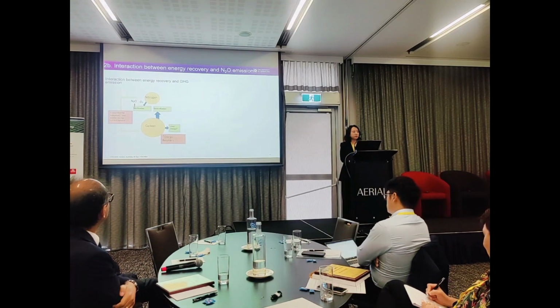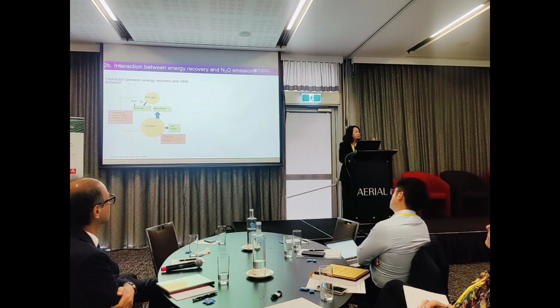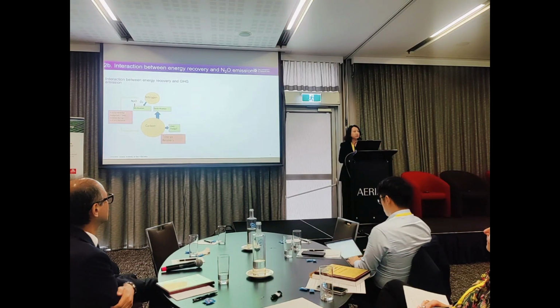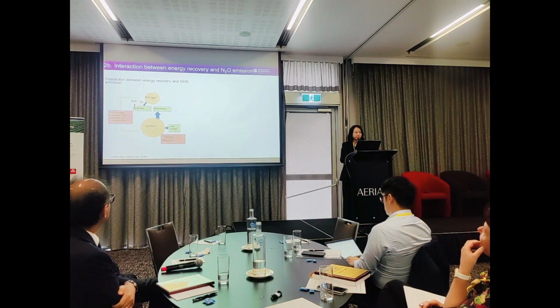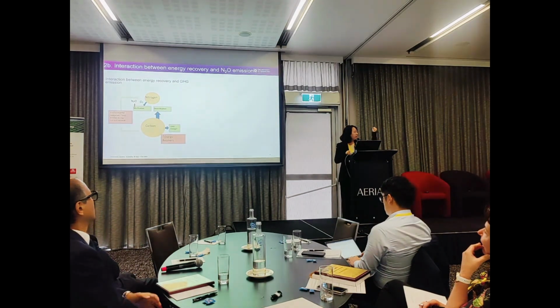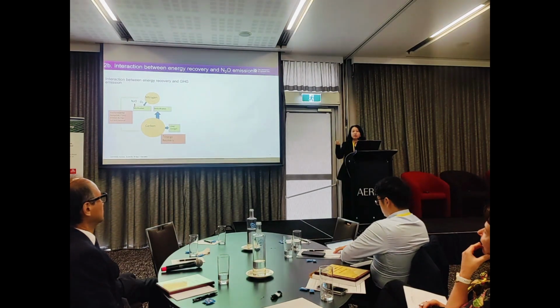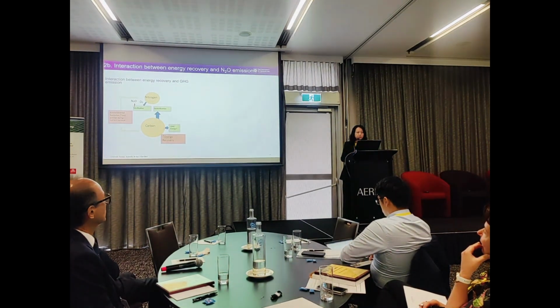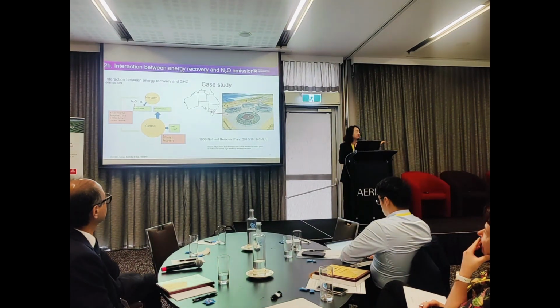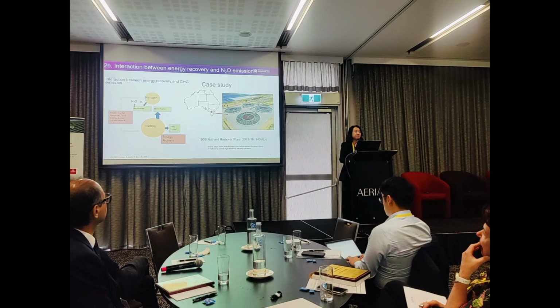Okay, the next thing I want to talk about is the interaction between energy recovery and nitrogen removal. When we try to promote more energy recovery, however, in our existing plants this carbon is also very valuable for nitrogen removal. That's what we need for the denitrification process. So there is competition over how we use the carbon. Do we want to generate more energy, or better nitrogen removal? Without looking at N2O, as long as we meet the percentage of removal, that's okay. But now there's a different angle, because we have N2O generation.